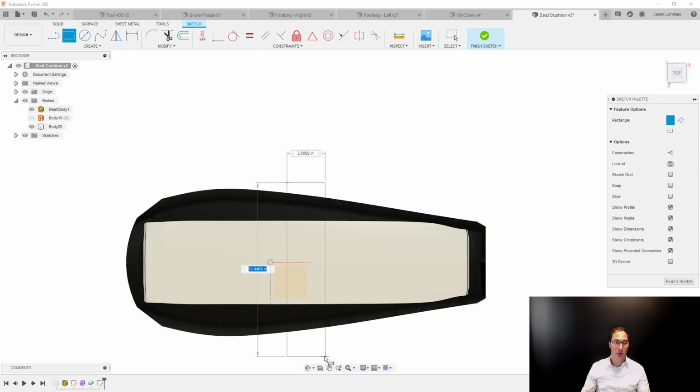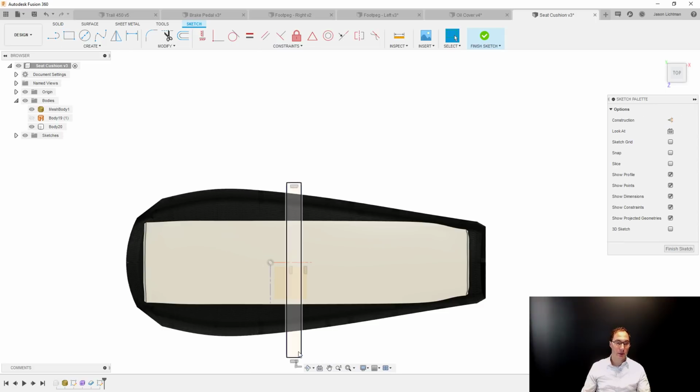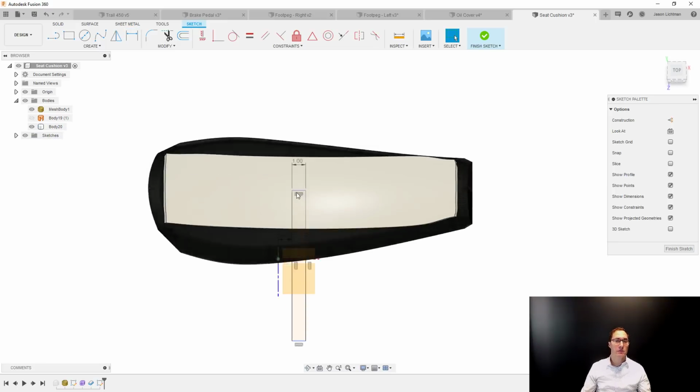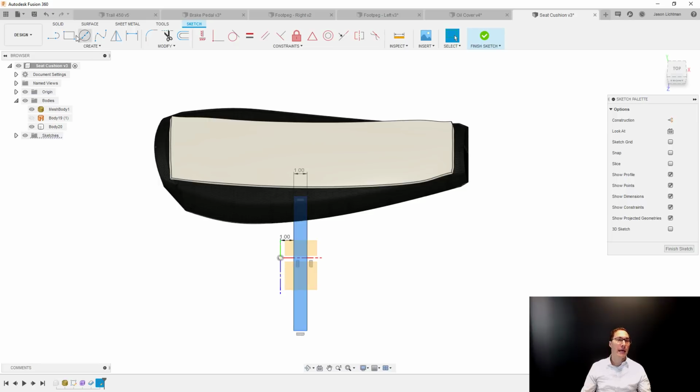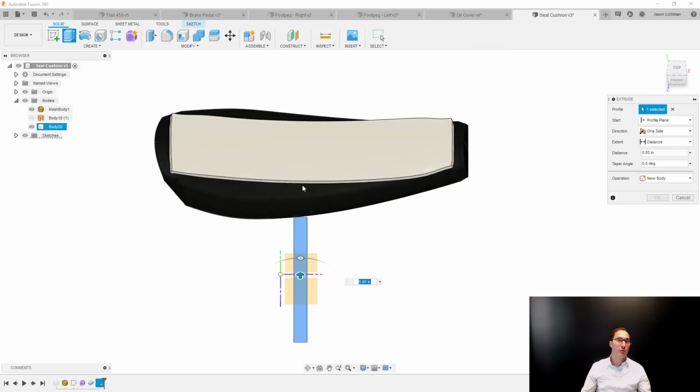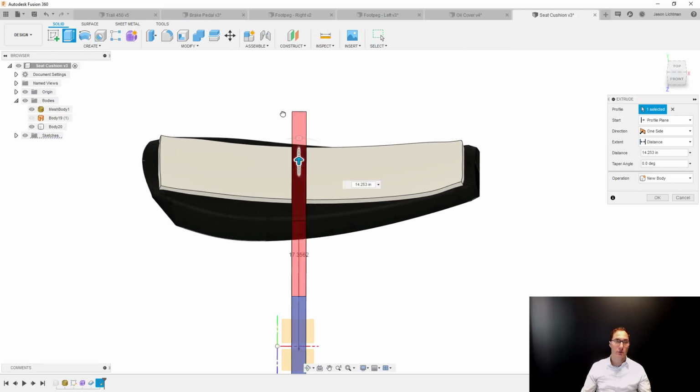a rectangle. Like I want maybe this handle to be in this location right here. Maybe I pick the dimension. I want this to be 1 inch wide. And I could position this exactly to maybe the origin or something else. It doesn't really matter. And I could take this sketch just like that, and I can extrude that through my solid. Let's go and do that.